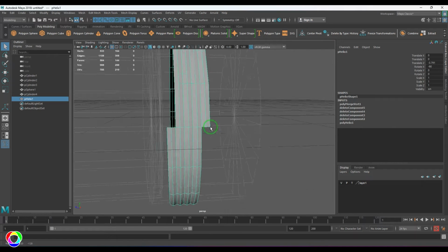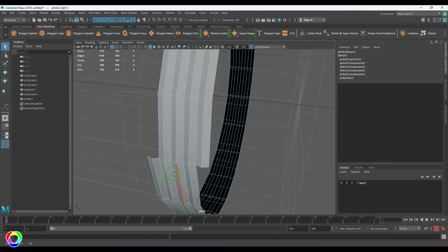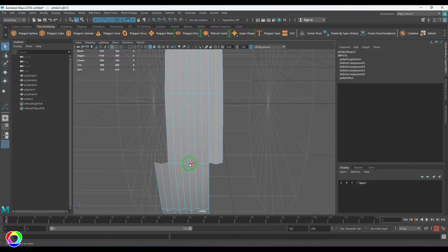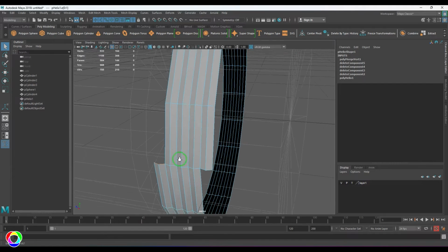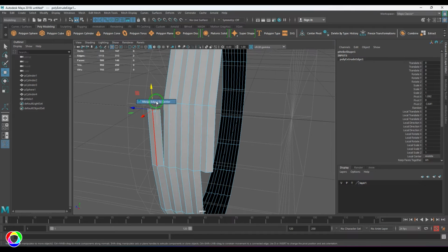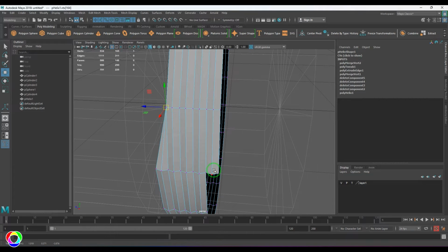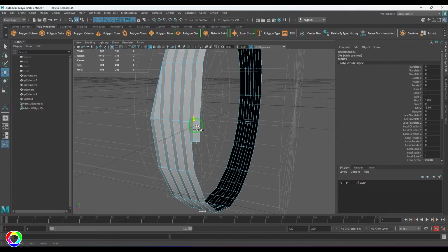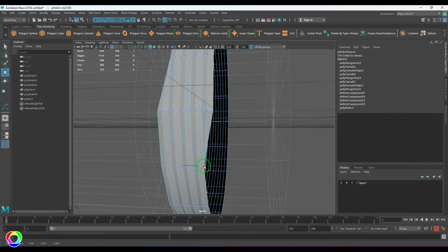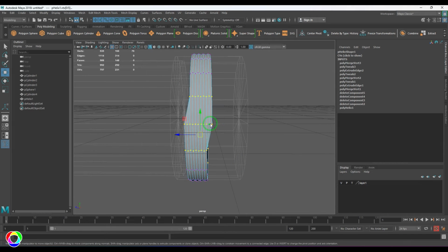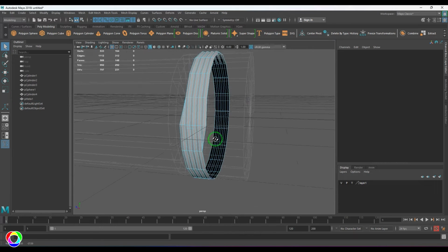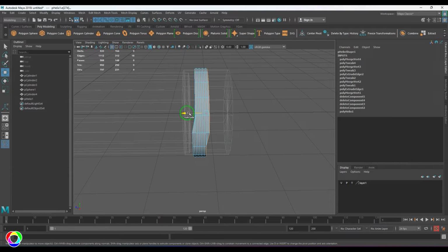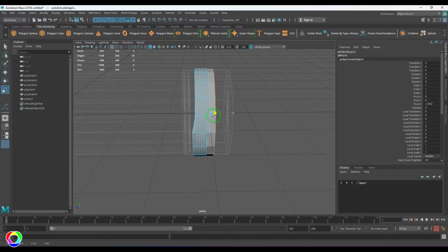That's pretty good. So I'm going to select these lines there. These lines will gradually become thin. Okay, that should become a blend. Okay, so maybe I can select this one here, merge to center, and then snap it there like that. Okay, and I'm going to select these two, extrude, merge to center, and then snap it there. Okay, and then I'm going to merge those vertex points, and that's good to go. Okay, and I'm going to select those lines and then extrude it and then scale it like that.